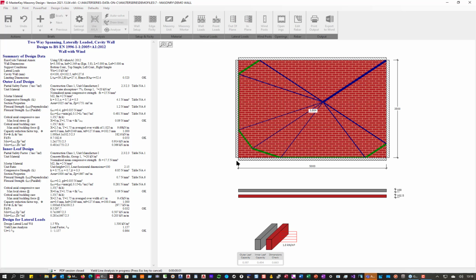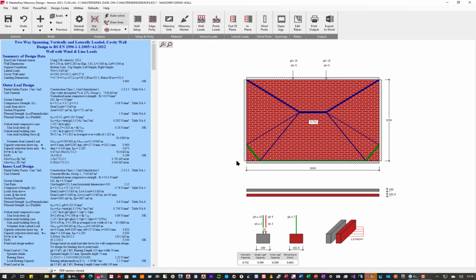And this next wall introduces something that's actually going to improve the strength of the wall and make it worse at the same time. And that is loading from above. Now, these are point loads. We'll deal with them separately in a minute. These are wall loads. So the inner wall, we have a concentric load from above, from a roof and a wall, and we have an eccentric load from this level.